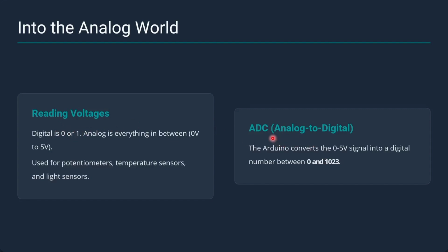Analog pins are from A0 to A5. They read the data from the sensor and transfer it to the Arduino as a value between 0 volts and 5 volts. This range is the raw data you work with whenever reading a sensor.